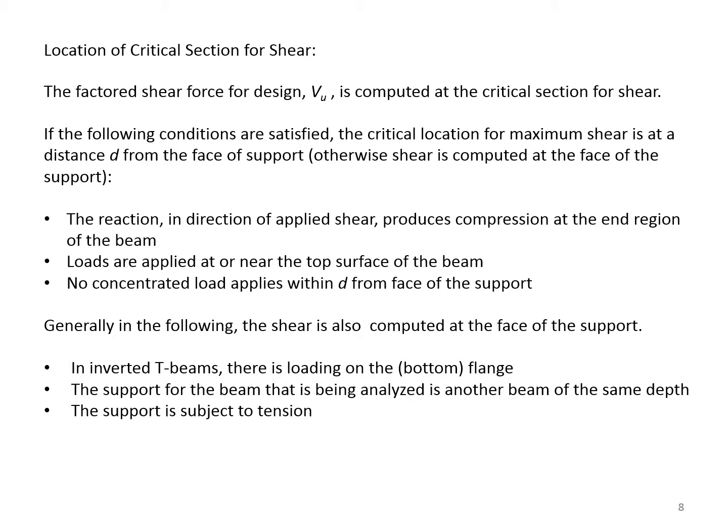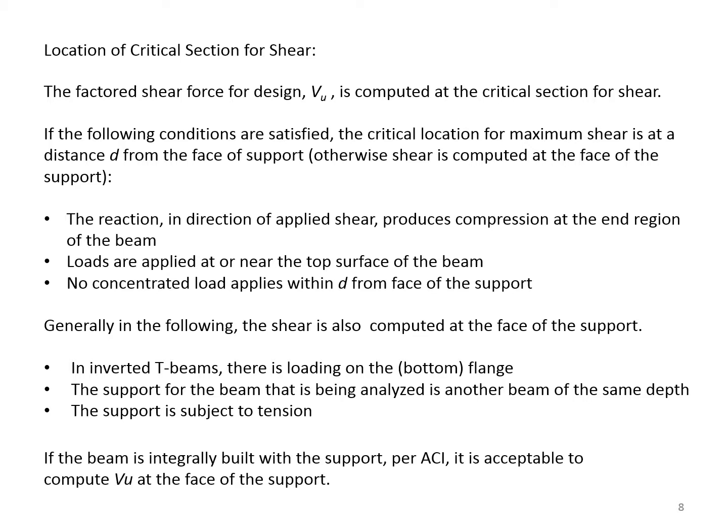Generally, in the following, the shear is also computed at the face of the support. In inverted T-beams, when there is a loading on the bottom flange, the support for the beam being analyzed is another beam of the same depth, and the support is subject to tension. If the beam is integrally built with the support, per ACI, it is acceptable to compute V sub U at the face of the support.